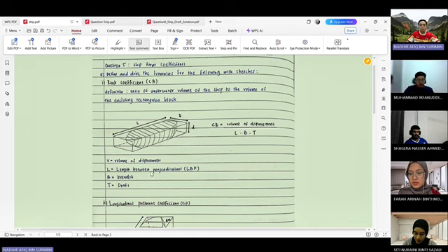The definition is the ratio of the actual waterplane area to the rectangular area defined by the ship length and breadth at the waterline. The formula is CW equals WPA over L times B.